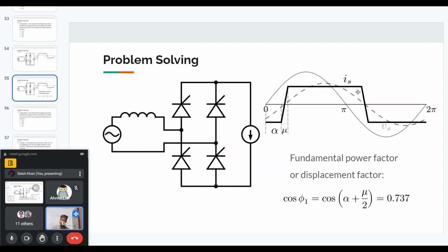The buck converter circuit basically has an input DC voltage, then we have a MOSFET, an inductor and the load. Between the MOSFET and inductor, a freewheeling diode is connected. If the switching frequency is given, then that will be the switching frequency of the MOSFET. I think we'll probably study choppers in future classes, but basically, the switching frequency will be the switching frequency of the MOSFET.